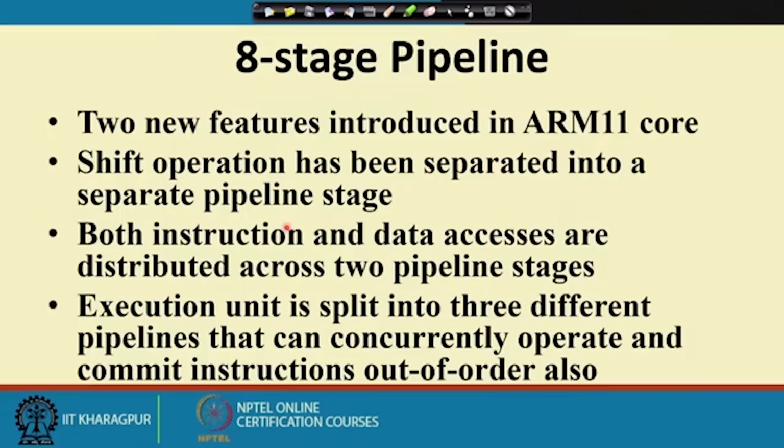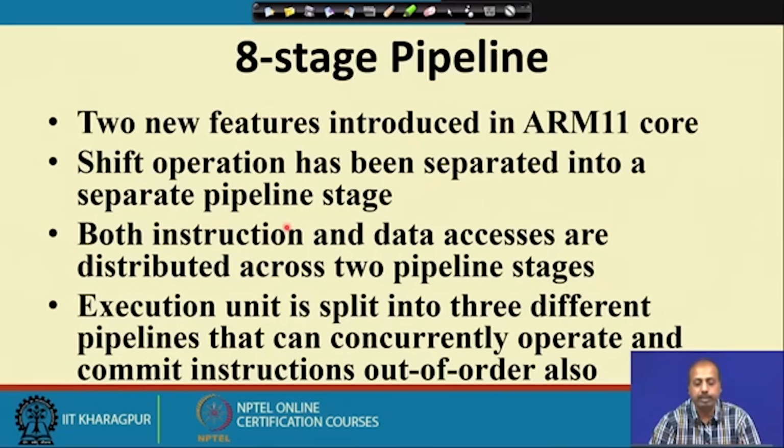Stage pipeline. So, this is another advanced version over that 6 stage pipeline. This is available in the ARM 11 core. There are two new features that have been introduced. First one is the shift operation. The shift operation has been separated into a separate pipeline stage.